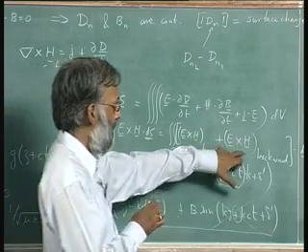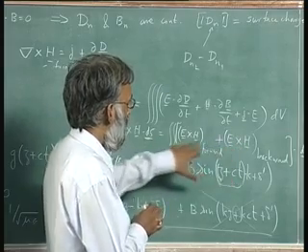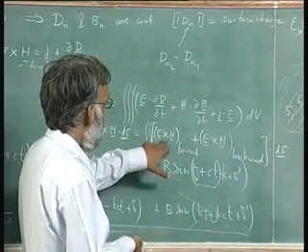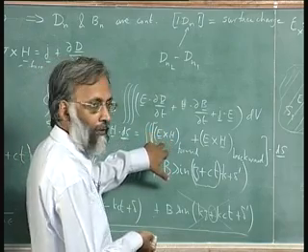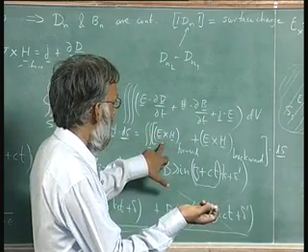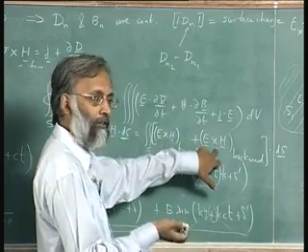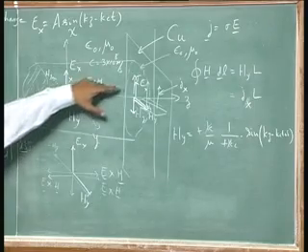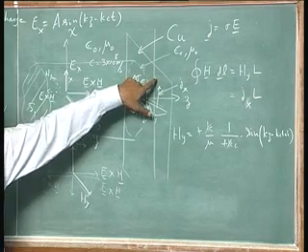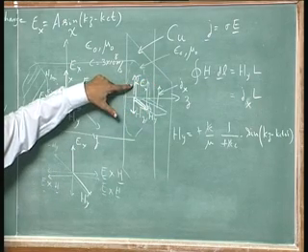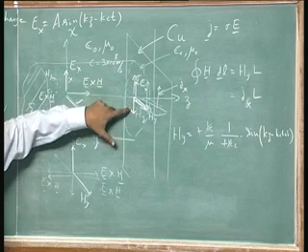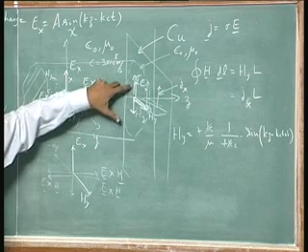Therefore, when I dot product these two with ds and ds points in the z direction, I am going to get the amount of power injected by the forward wave minus the amount of power taken away by the backward wave. But in order to make the electric field 0 inside the wall, I had the reflected wave and the incident wave, these two waves equal in power.